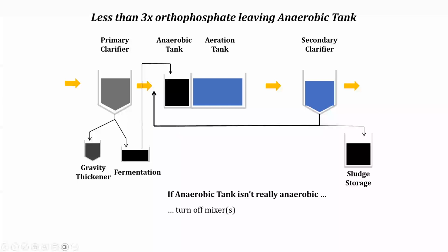And to fix conditions for the ORP is really easy. Turn off the mixing and allow some solids to settle to the bottom of the tank. And as they settle, in that settled portion, it's going to be much further away from the surface and therefore from the air exchange, because it's a non-aerated tank, and it's more concentrated. So the organisms are going to be breathing any air that might exist to stay alive. So the ORP is going to drop better in that bottom zone.